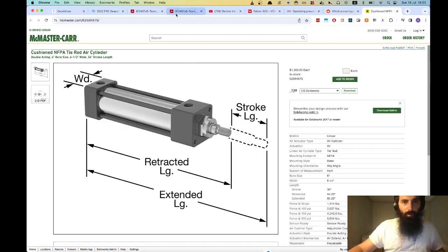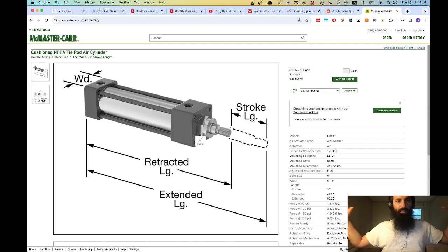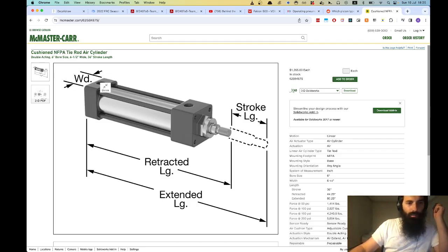So what you do is on the robot, you have a compressor. And what it does is it takes air from the outside and it compresses it and highly pressurizes it. So there's highly pressurized air, and you keep this in a kind of container. And you'll see here that there are two holes. So this right here is one example of a cylinder with an input and an output tube or hole. So here, this piece right here is free to go in and out, in and out. It's kind of free sliding here.